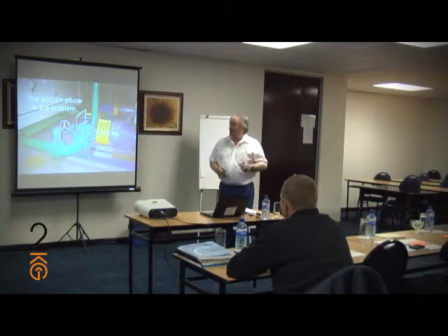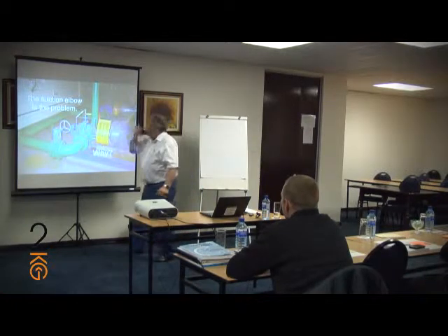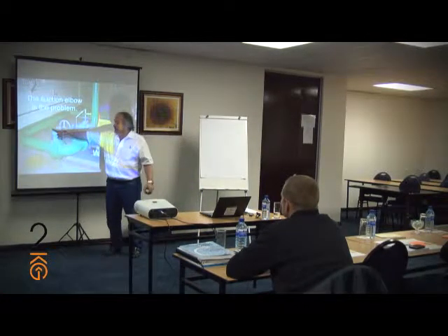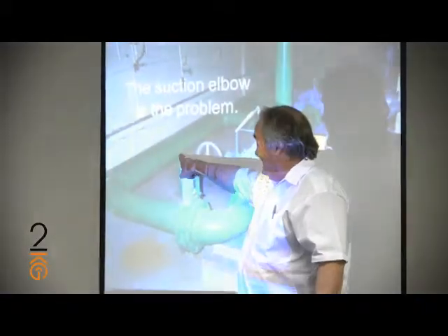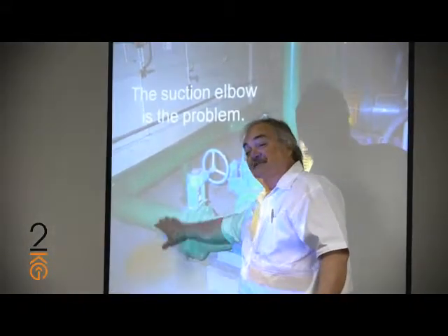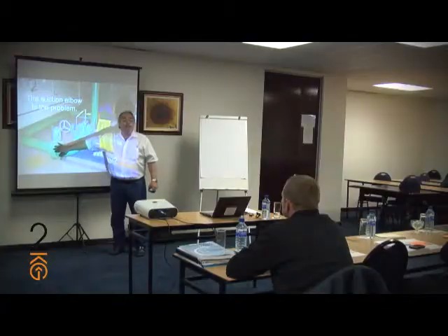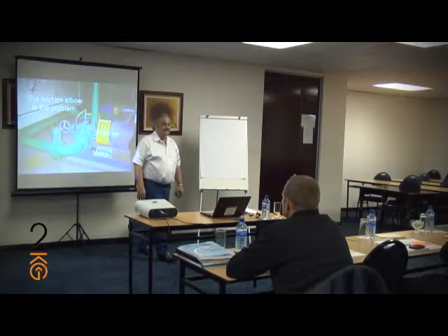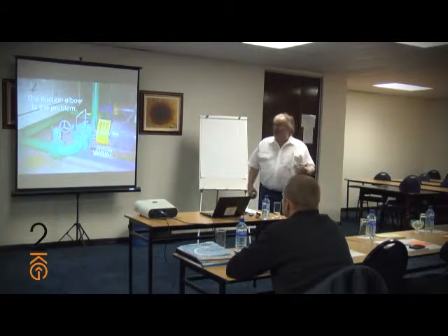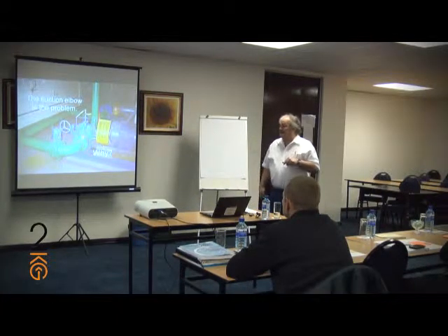Now there's a couple of other problems. I'll just point them out to you. The last pipe support is back over here, okay? There really should be one about here. So that's your last pipe support, and this is the wrong valve. So it's got a couple of problems, but the biggie is this thing right here.